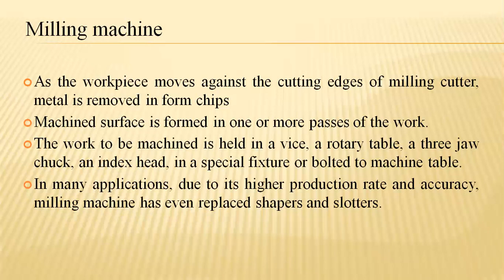But when harder materials are utilized, such as cast iron, mild steel, etc., automatically HSS tools, diamond-shaped tools, PCBN tools and PCD tools play a major role in order to machine the objects for getting particular shapes of the material, even flat surface finishings, diagonal edges, parallel edges, or any of the contour positions at different places of the object.